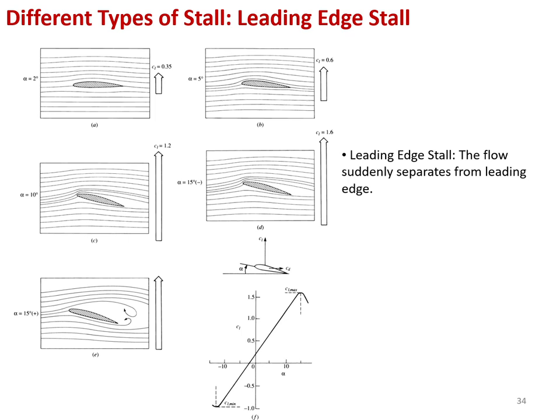So leading edge stall is where the flow suddenly, and suddenly is the key term here, separates from the leading edge. When the flow separates from the leading edge, you're going to see the separated flow over the airfoil. So separation doesn't start from the trailing edge and move towards the leading edge. It starts from the leading edge, and there will be a sudden expansion of the separated flow to the whole airfoil. So, sudden separation of flow from the leading edge.